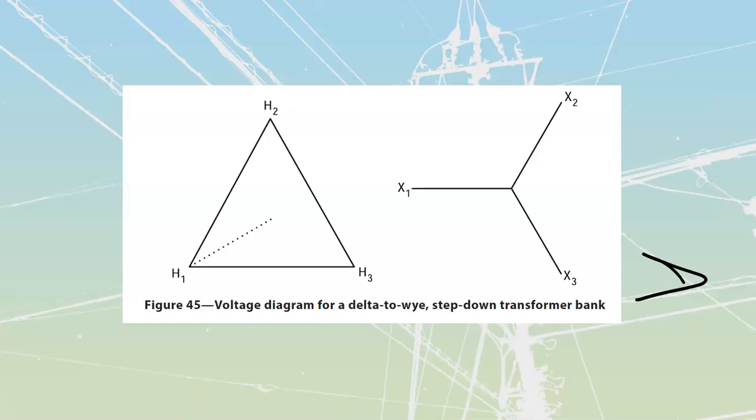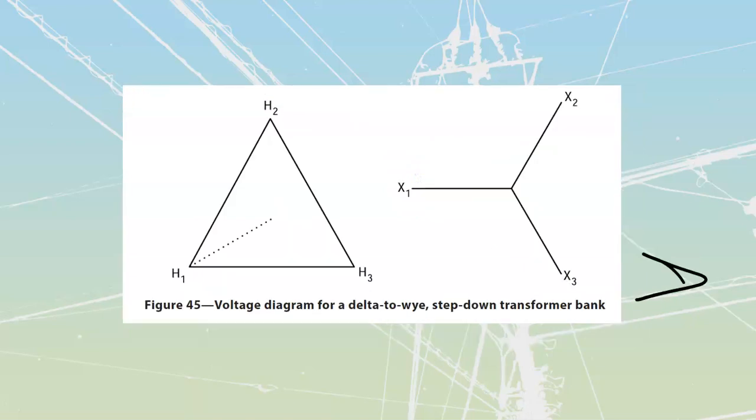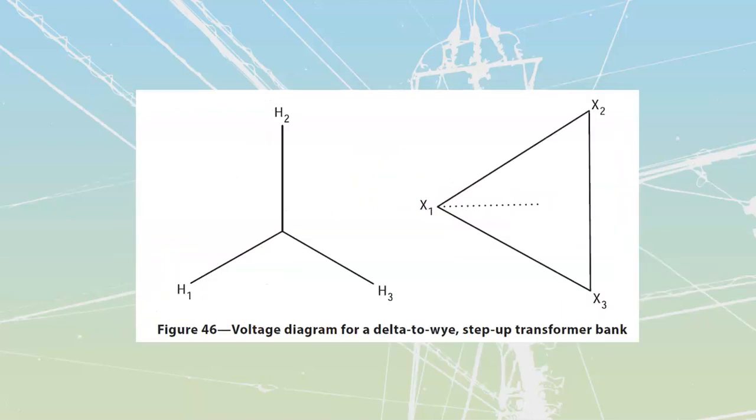I do want to note that on both this one and the subsequent drawing over there, you should be noting that 30-degree displacement that was put in last video. You noted that there was a neutral and that our A to neutral was 30 degrees off the horizontal on our high side, and then we took that A to neutral that was existing and moved it up by 30 degrees. So my A to neutral was a 30-degree displacement from my high side to my low side. And the same with this one over here.